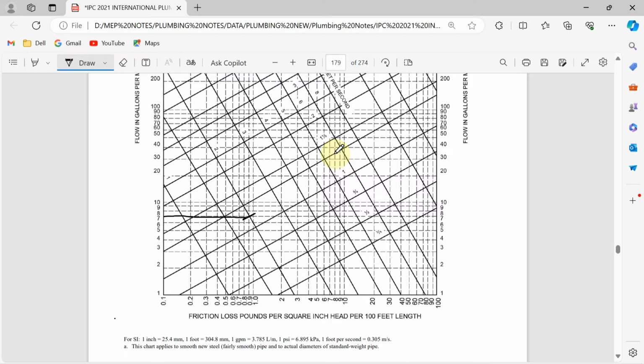But when I'm selecting the larger size, what happens? This is the water supply line. Because it is coming between these, now the question is, do we select the 1 inch pipe size or 1 by 4 inch? It depends. Remember, always for water supply line you have to select the minimum pipe size. It is better. Why? Because here we need pressure. But in our condition, this is gravity water, already we are getting gravity pressure.